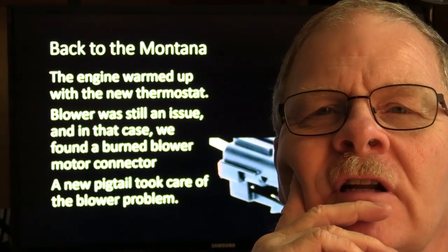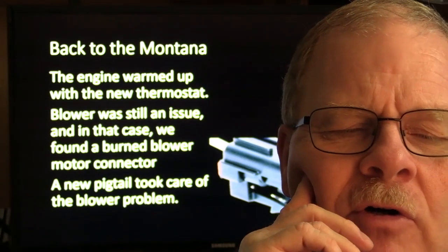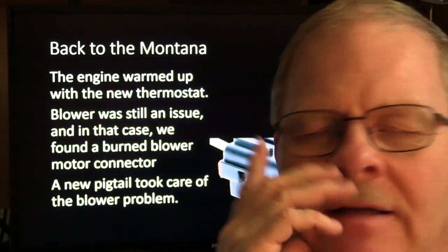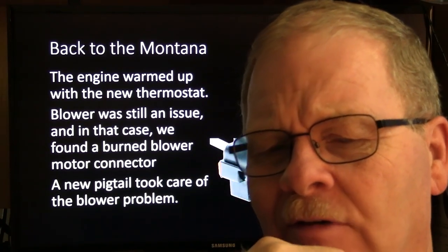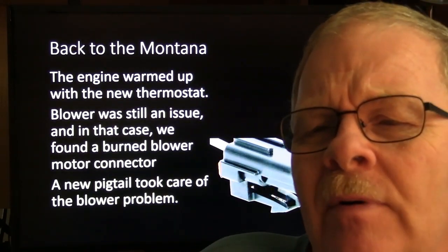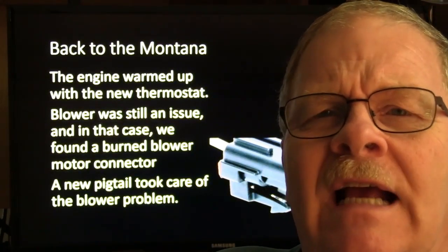Now, I had talked a little bit before about, you know, the old Motorcraft number was WA10, but even if you look that up now, you'll see some of that dielectric grease, like using on spark plugs. Ford likes using it on brake calipers now because it's kind of heat resistant.